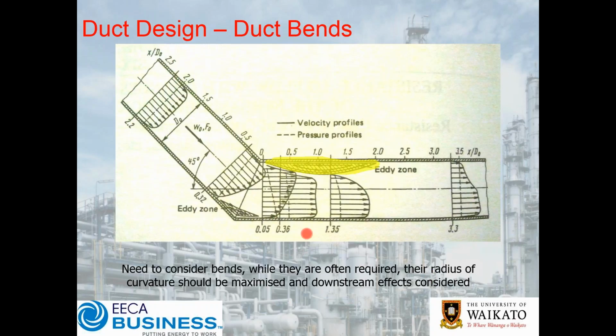And so you want to be very, very careful in looking at bends, where they are often placed and how they're radiused. Now, as a general rule of thumb, with a miter bend, does that bend need to be a nice, even, curved, swept elbow? Well, if it can be, great. However, if you have a 3 or 4 piece lobster back or miter bend, as opposed to that 1 miter bend, you'll find that just 1 or 2 extra miters on that bend will make the world of difference to the flow around it without having the expense of a fully swept, curved elbow.